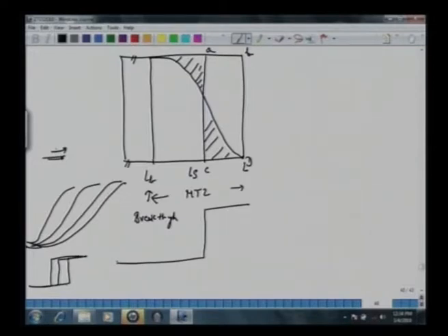So what we experience in a practical sense is a curve like this, which is non-ideal. Had this been ideal, our breakthrough curve response would have been like this. So there is a non-ideality. What we see here is a profile like this. There is a certain region which becomes active ahead of this TS, and there is a certain region which is also active after this TS. This is all because of the dispersion effect.